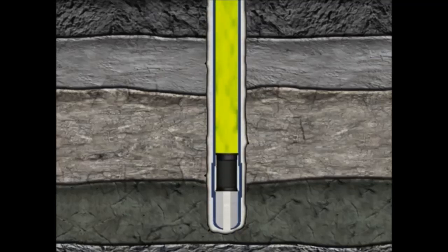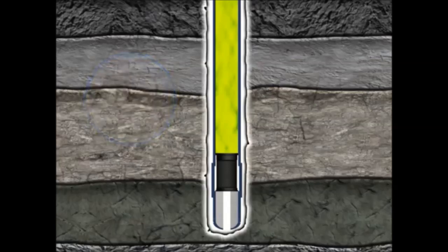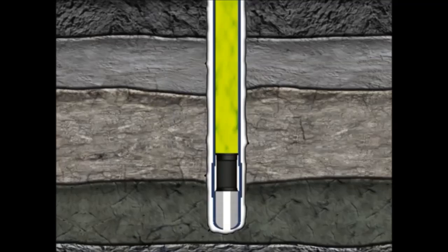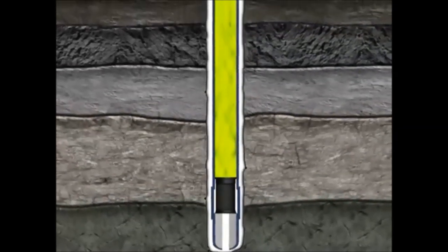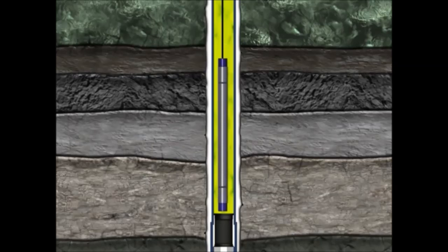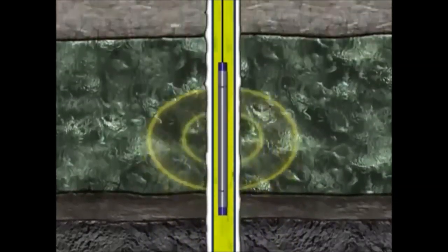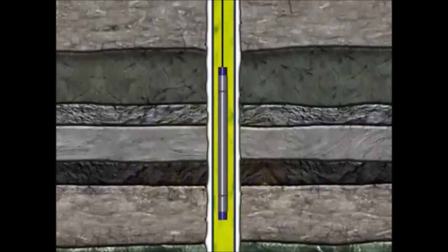To allow further operations in the well, the cement requires sufficient curing time. The cementing process is not always a flawless operation, and the resulting cementing job might contain some bonding issues that would undermine the strength and integrity of the casing, especially during perforation. The bond of this cement with the formation and with the casing is evaluated using a cement evaluation wireline tool. This tool determines whether the cement job is optimal. If not, further remedial operations are required.